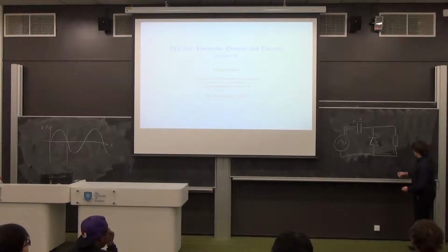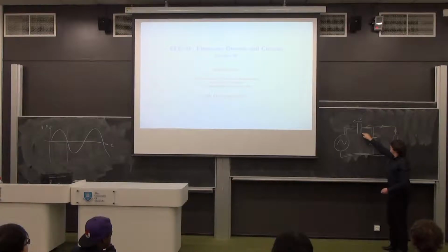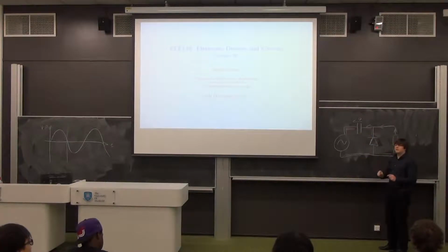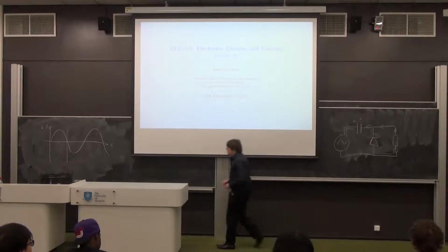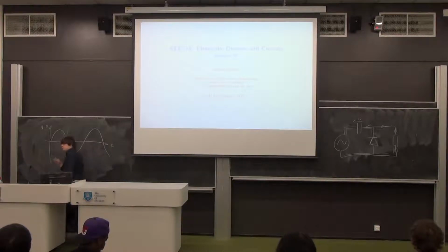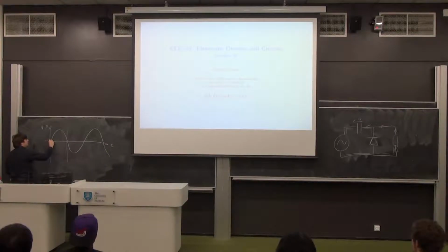Currents will be in yellow. A small current goes up there, down there, and down there, and makes this plate more positive than this plate, ever so slightly, but hardly anything at all. Basically still 0 volts across the capacitor. As a consequence, the output voltage, which we measure across RL and will be in blue, just does that. And this situation carries on until we get to minus 0.7 volts, which is the turn-on voltage of the diode.